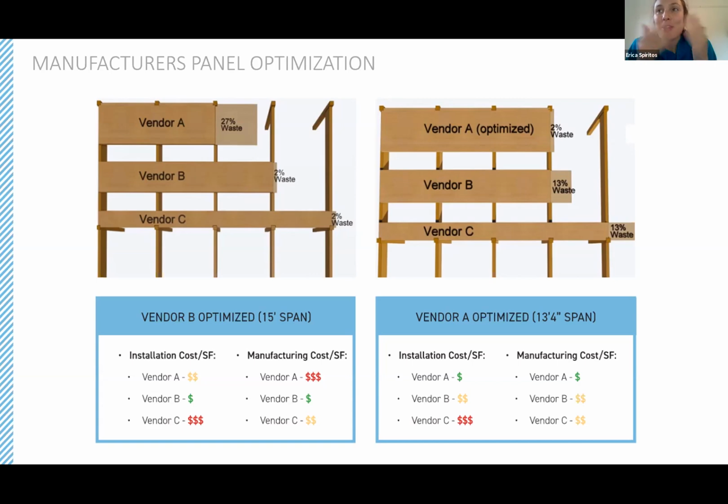The topic of this case study is design and procurement implications of design. One thing to note is that when we set our grid spacing, our glulam frame layout, we are inevitably making a decision that will benefit one manufacturer over another. We might not know that we're doing that, but it's good to be aware of the implication of that decision.